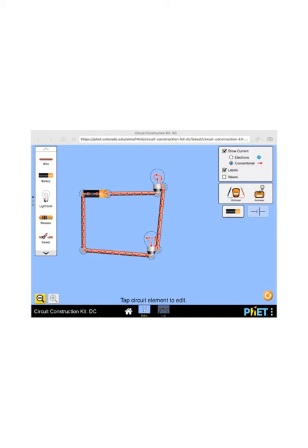And now we get much smaller, fainter yellow lines. Two light bulbs connected in the same circuit give a much dimmer glow. If I measure the current in this circuit, I measure a lower value, 0.07 amps, compared to the 0.15 we saw before. It doesn't matter where I measure that current, I'm still at that lower value.